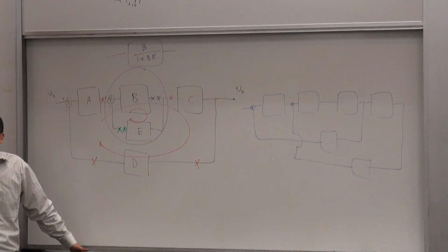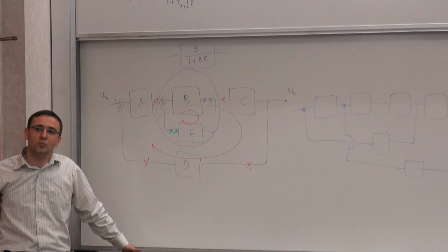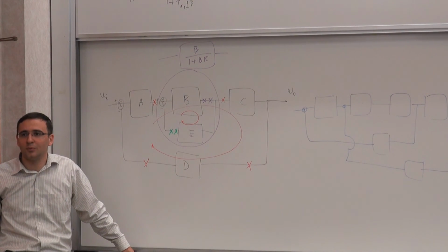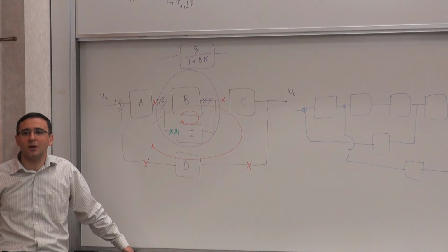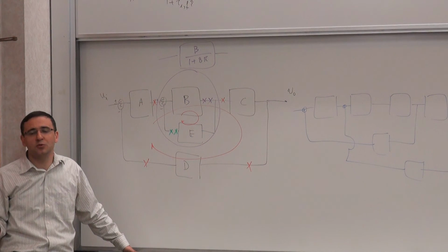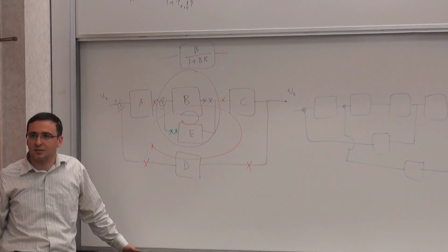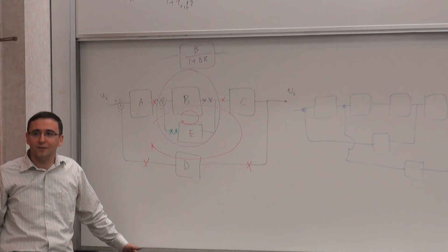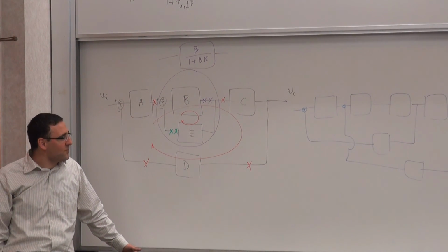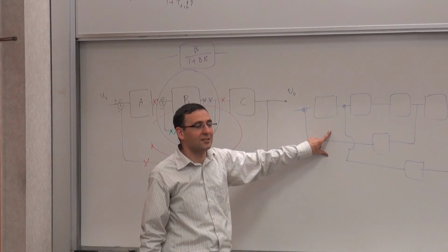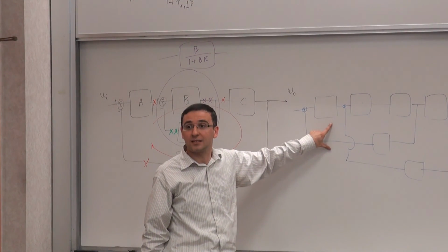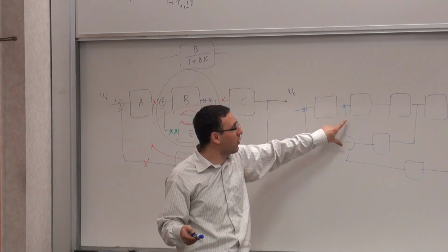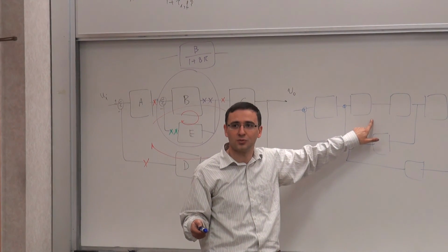There are ways to relate the loop gains of inner loops and outer loops, the equivalent of Mason's rule but for loop gains. But it just becomes too complicated. So what people do is basically just break it down into smaller pieces as much as they can. Now, in circuits, part of the reason, and it's like a chicken and egg thing, is that you don't see a lot of these kinds of things. You see nested multiple loops, like nested Miller compensation and things like that, but you don't see a whole lot of crossing loops.